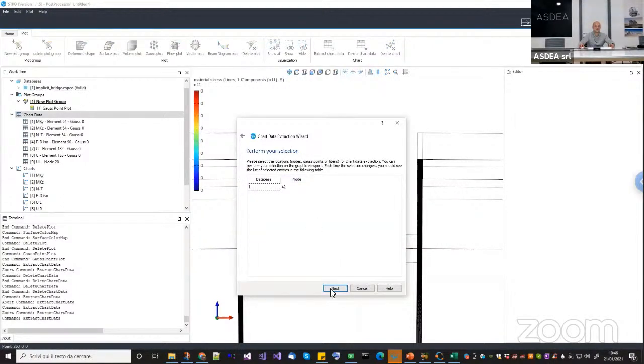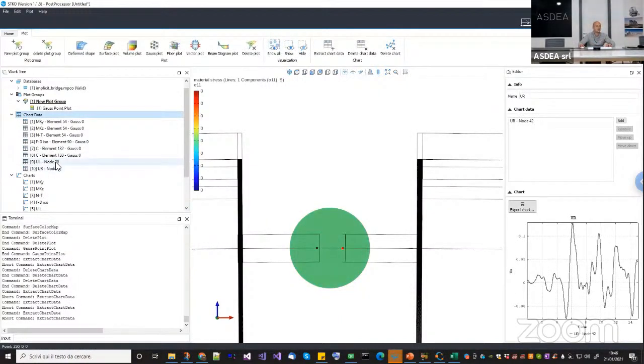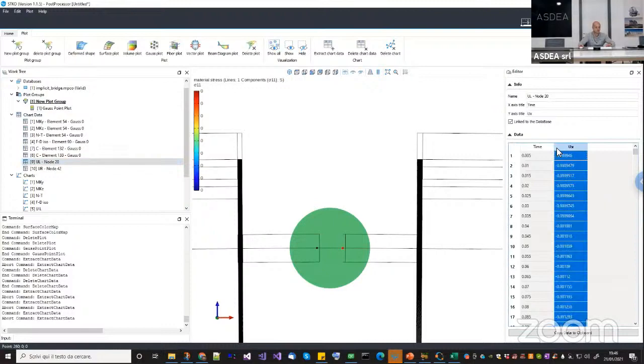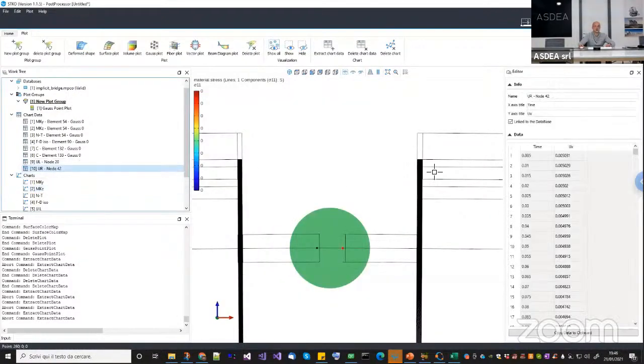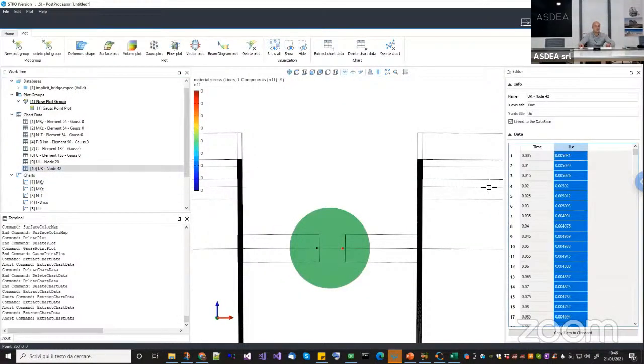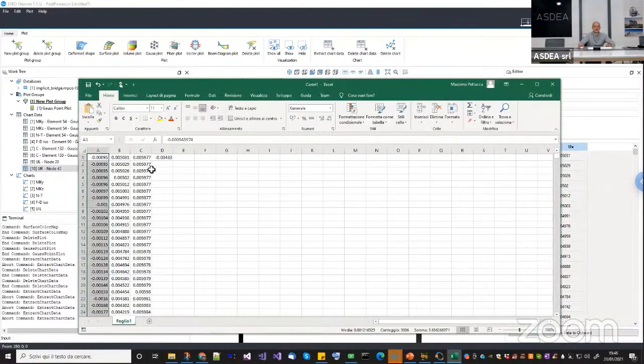Next, UX right. Okay, now let's go here, UX left, copy and paste it. Now, okay, now it's changed. Yeah, probably there was a mesh renumbering. Then copy this one and paste it here. And as you can see, the compenetration is almost 0.